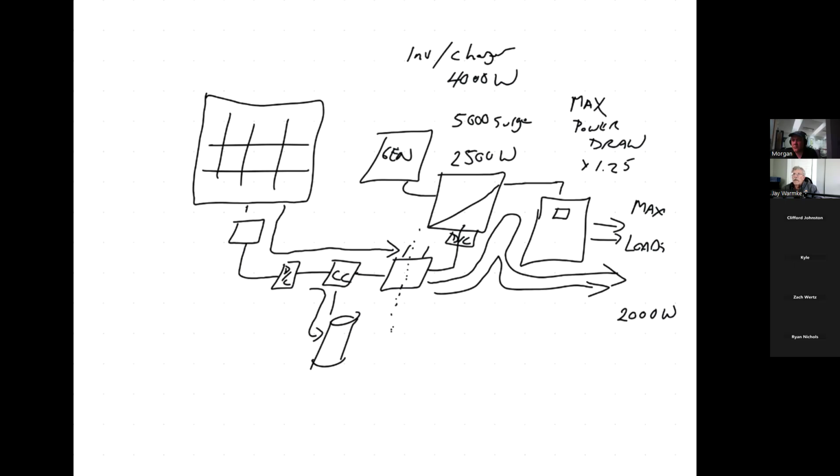So it's generating power to your inverter, and then the inverter is recharging the battery, and the battery is servicing the load. Okay, so that's what the generator is doing, and that's what's being controlled within the inverter. So you're not running the generator directly to your loads. That's not happening in most of these cases. It's simply recharging your batteries.